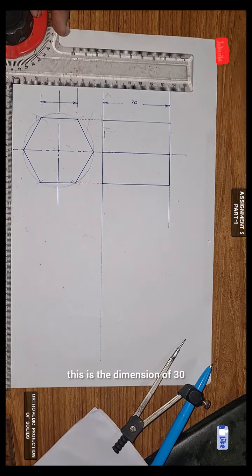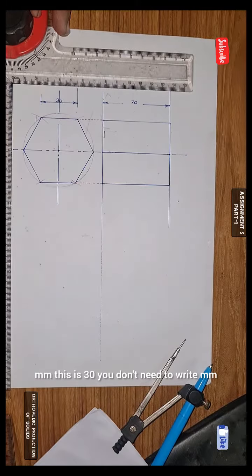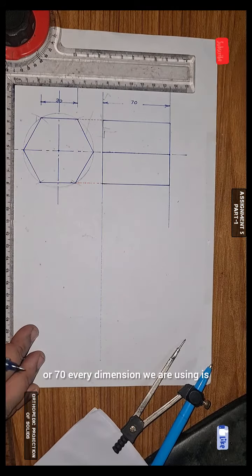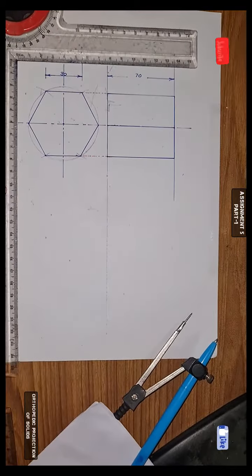This is the dimension of 30 mm. This is 30. You don't need to write mm. You just need to write 30 or 70. Every dimension we are using is on the basis of ISO standard. So that's why you don't need to write it anywhere.